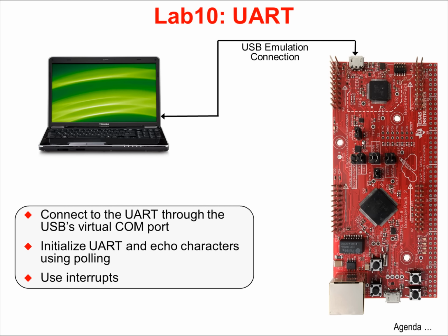Lab 10 experiments with the UART module. On the LaunchPad, the UART port is connected to the emulation hardware, which then connects through the USB port to your PC. On the PC, the UART connection will appear as a virtual COM port. The lab will initialize the UART and use polling and interrupts to echo characters.